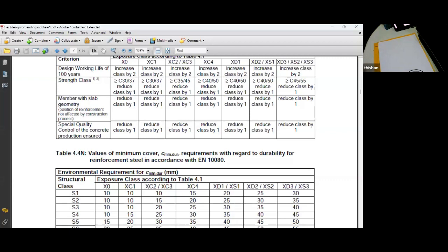But if you want to have a really thin slab, you want to optimize it, then you need 25 millimeter cover for the slabs. And then you have to buy a cover meter and when you are doing the concrete, do it carefully so that 25 millimeter cover can be verified and assured. So that is the situation. But if you are doing, say, a 150 millimeter slab, keeping 35 millimeter cover will assure a building that will not have any problem over a very long period.